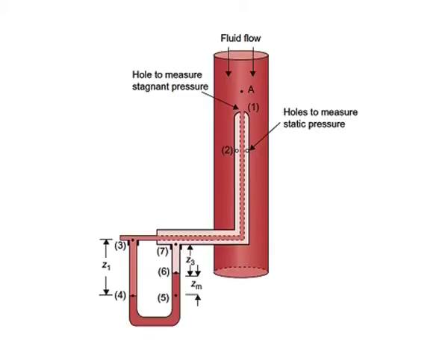If a U-tube manometer is used with the pitot tube as shown in the figure, then we can follow the same approach as given earlier in this section to account for the pressures at various locations. We can measure the velocity directly from the change in height of a manometer fluid, that is Zm, when the two sides of the U-tube manometer are connected to the two outlets from the pitot tube.